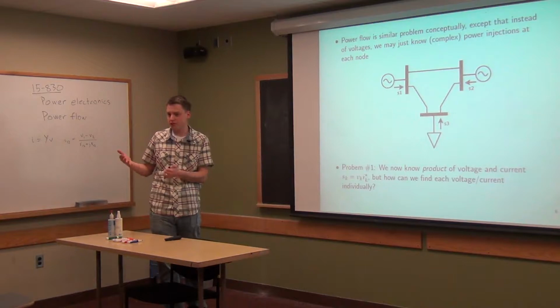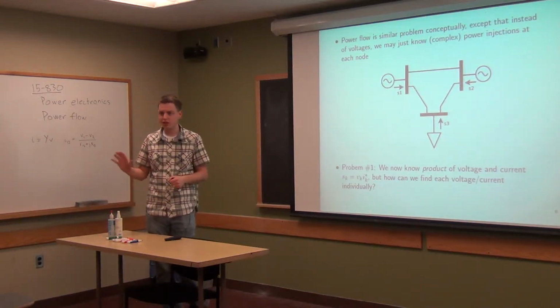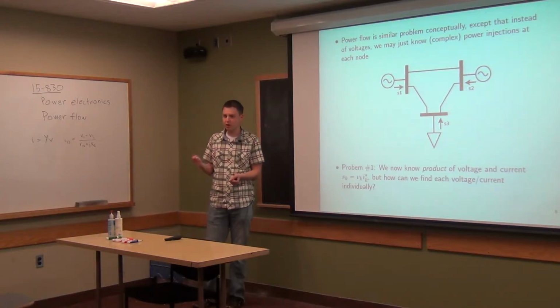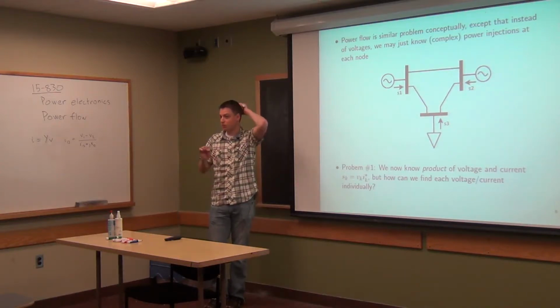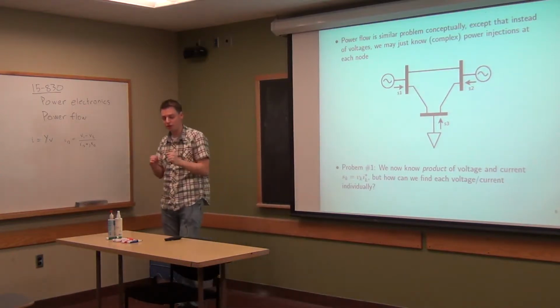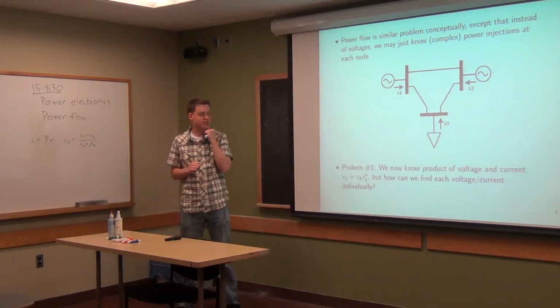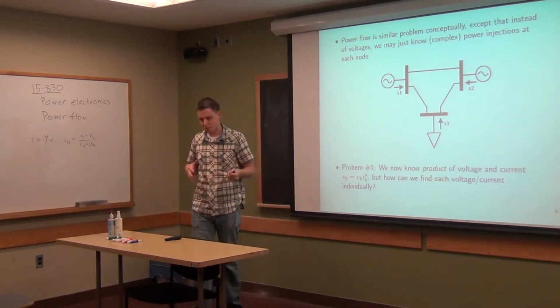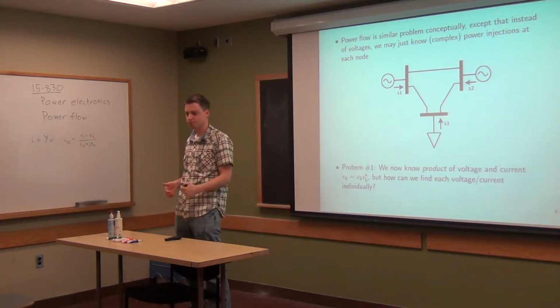We can control the voltage a little bit by adjusting the voltage of that electromagnet that was spinning in the generator, adjusting the absolute voltage, not controlling the imaginary and real components of that voltage, just controlling its absolute magnitude. And we can control the real power that's being output, right? That's just the actual amount of mechanical power we put into the system.